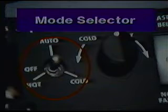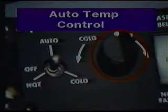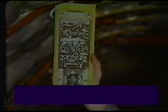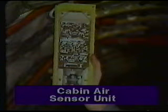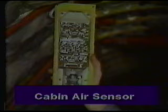Controls in the cockpit include the mode selector, sometimes referred to as the auto manual selector, and the auto temp control, sometimes called the cabin air temp control. The unit that houses the cabin air temp sensor also contains the electronic control portion of the system. It is therefore properly called the temperature system control and cabin air sensor unit. It is most frequently referred to as either the control unit or cabin air sensor.